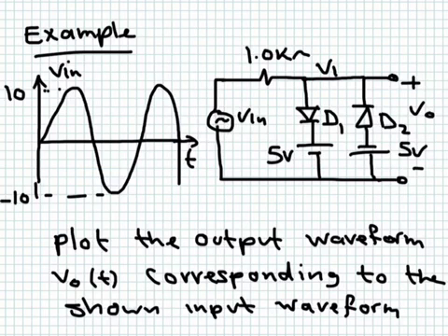If you have 2 volts here, with this polarity, is this sufficient to turn this one on? No. Why? Because this is added to this reverse voltage. This is negative positive, this is negative positive. So the reverse voltage applied to this one even becomes 7 volts. So this one doesn't turn on. So when the voltage reaches 5.7, this is when this one will conduct.